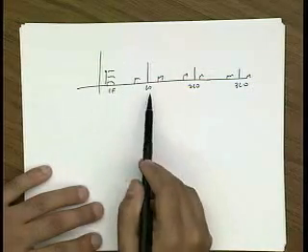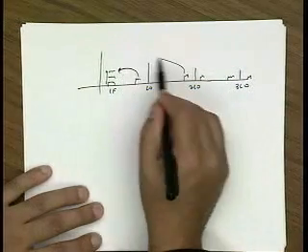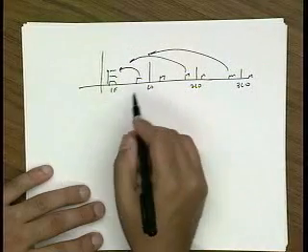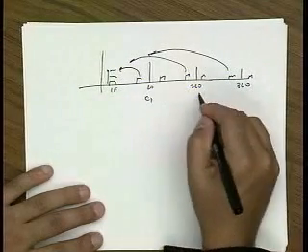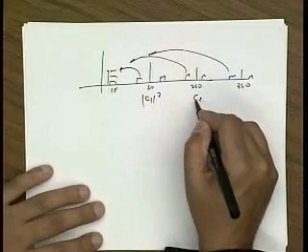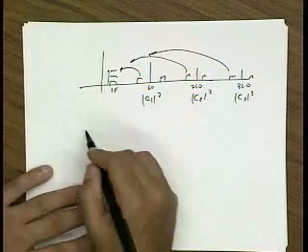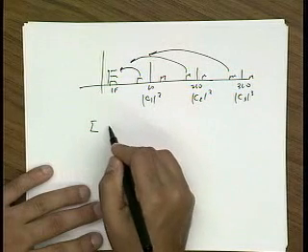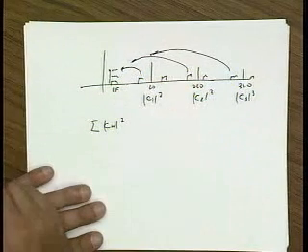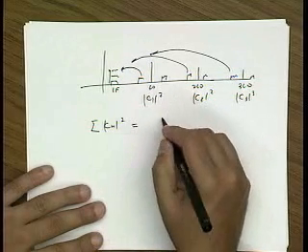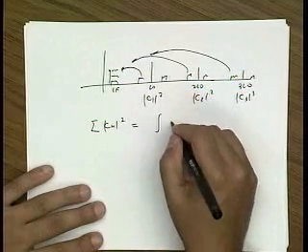So I'm going to sum up all these noise contributions. And if I do that, the gain from here is C1 squared. The gain from here is C2 squared. The gain from here is C3 squared, right? So the total power is the sum of Cn squared, right? And by Parseval's theorem, we know that this is basically the energy of the signal.